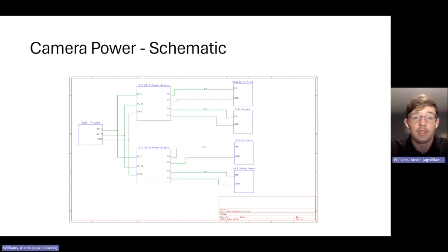And then moving on to the schematic here, this one is also just a basic connection because of the lack of the power subsystems that Dr. Austin has stated. But we're going to be transforming wall power with a 5 volt output transformer. That transformer is 100 watts and 20 amps, which is a bit overkill, but we would rather have too much than not enough in that scenario. And the price difference is not really a consideration because it's just a few dollars for that extra wattage. But we will be powering a Raspberry Pi, the camera, and the motors all with 5 volts.